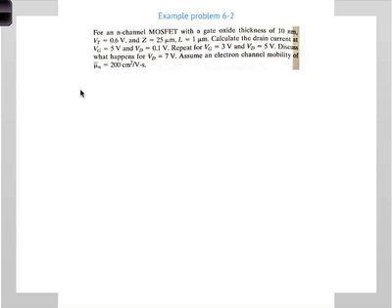Okay, good. So it's a very typical problem, so let's walk through it fairly quickly. You have an N-channel MOSFET with a gate oxide thickness of 10 nanometers. So it's pretty big for a gate. Remember earlier we talked about 1 nanometer and so on. The threshold voltage is 0.6 volts, so that's very typical. It's typically between 0.5 and 1 volt, and we will talk more about this later on. It's the most important parameter that you get to play with in your transistor design.